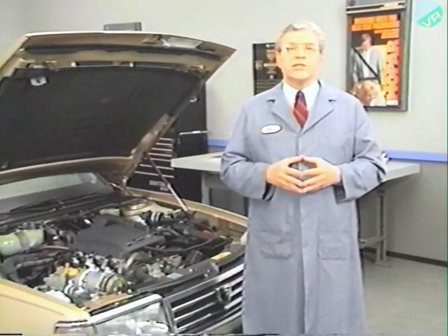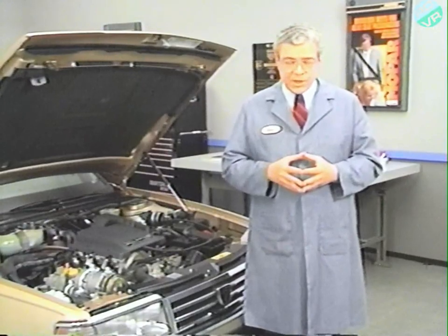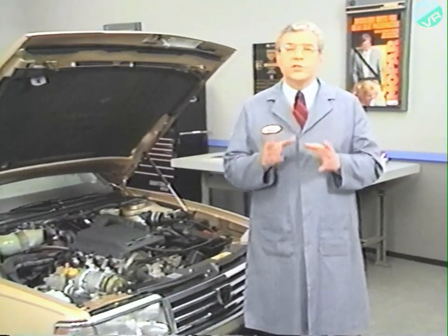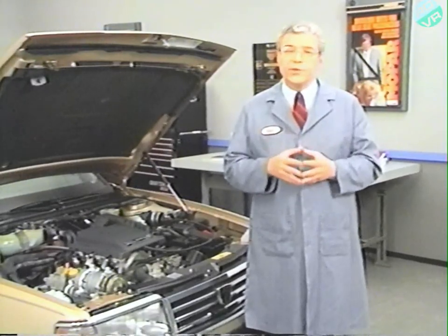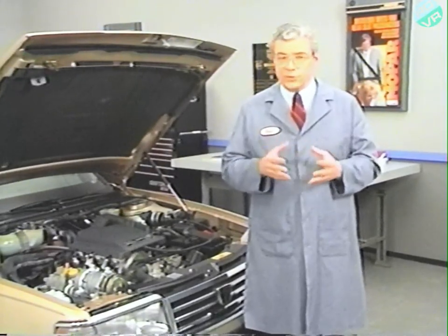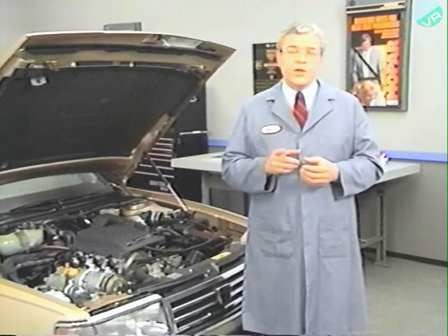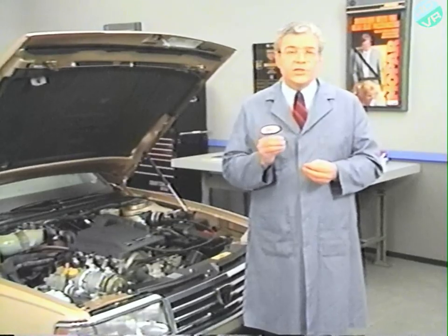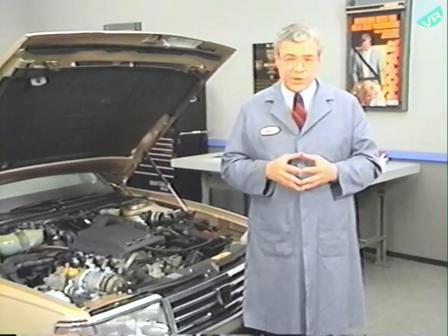Earlier, when discussing the ACM-ECU links, we mentioned something called blower delay. At this point, we need to explore this unusual feature of the Premier and Monaco climate control system in greater detail. First, with a climate control system equipped with AC, the following conditions must be in effect for the delay to occur. The controls must have been left in heat or heat defrost.